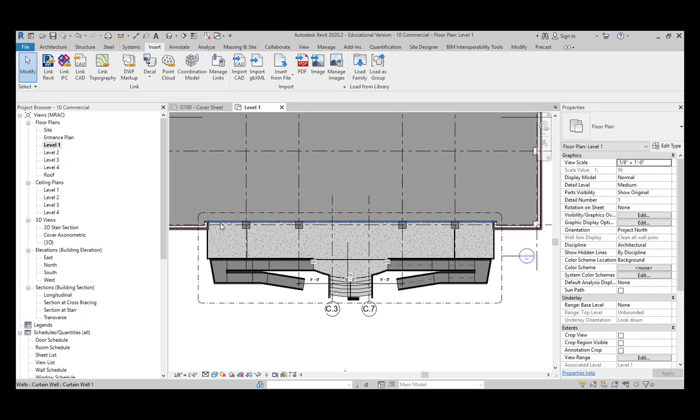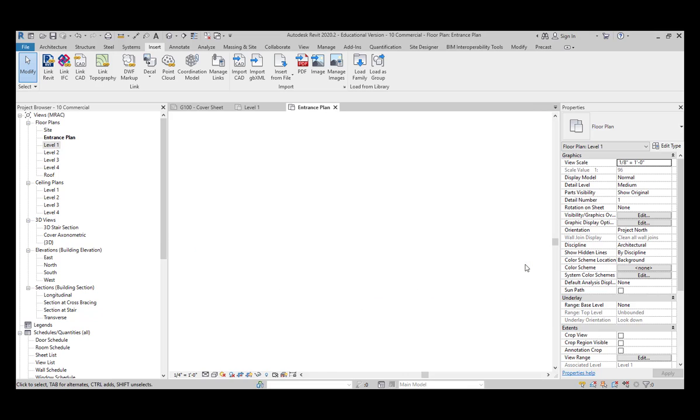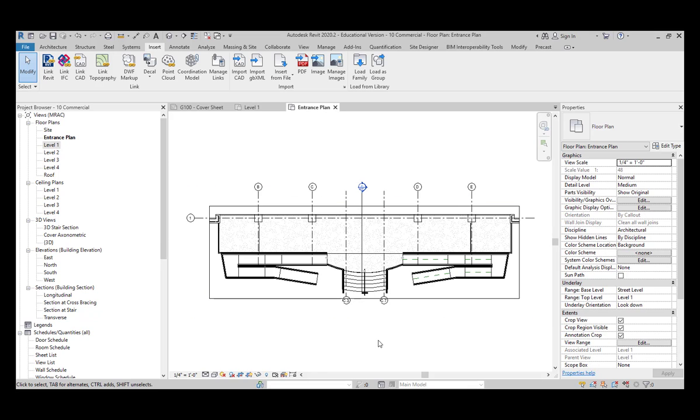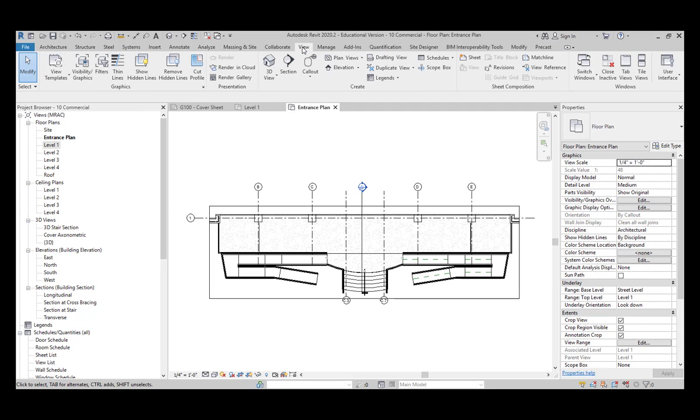Is at 435, and then once you're to that point, you can move forward and start adding the grids. But I want to save this view. So you'll notice there is this enlarged plan view, and if I click on that, it's going to take me to a cropped region of the plan. The way they built that was to go up here to the View tab, and they created a callout.